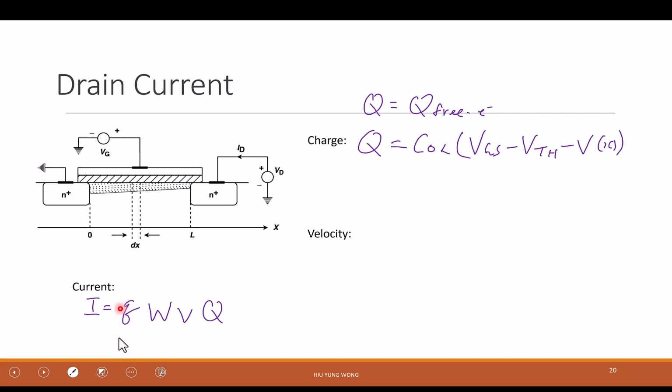Well, it depends on how much water each truck carries. This is Q: how much charge each electron carries. How wide is the freeway? Two lanes, three lanes? What is the velocity the trucks are driving? And what is the density of the trucks? Yeah, you're driving fast, but you only have two trucks every 100 meters. Your density is small. This density comes from this. So similarly, what is the density of the electrons, which depends on the capacitor? How fast they are moving, how wide your transistor is, and the charge they are carrying.